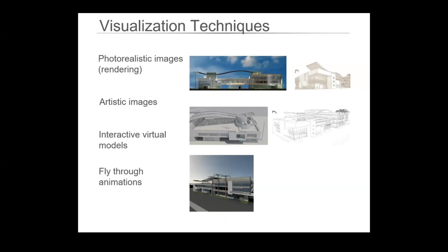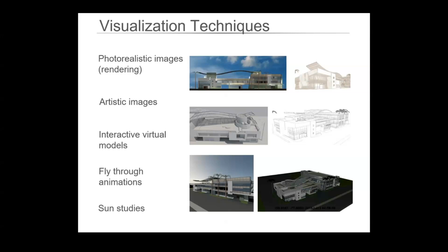And then we've got the fly-through animations. It's a basic thing that ArchiCAD can do itself, so you can set up pathways. If you want to set a pathway up through a building, you can place cameras in sequence and set times so that it can just wander through the building and create a little MPEG or video file of some sort to show your clients.